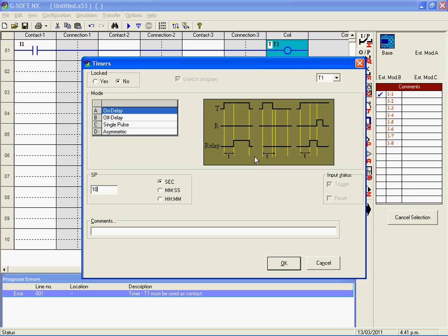If the duration of the trigger pulse is less than the operating time of the timer, then we will get no output as shown on this timing diagram. If we want to shorten the length of the timer output, we can apply a reset to chop it off. Otherwise it will stay high until the trigger input goes low.